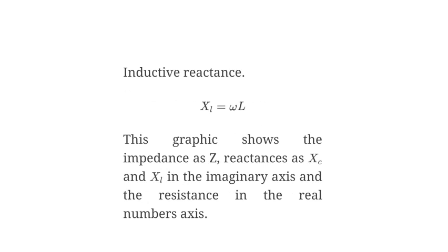Inductive reactance is the corresponding term for inductors, and this reactance is XL is equal to omega L. Remember this. In capacitance, this omega came in the denominator, but here it is in the numerator.